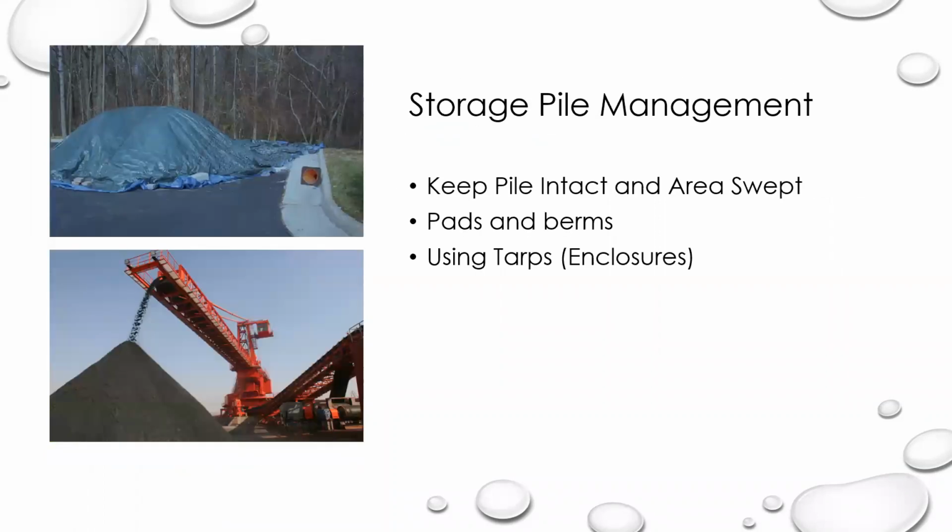You also want to manage your storage piles. Again, I've mentioned a few times, you want to keep it covered. But it's important to know if you're getting from it often, you want to make sure that you're sweeping the area around it and keeping that area nice and clean. You want to have pads and berms related to it and tarps and enclosures if possible. And of course, if you're constantly using a pile, this is not something that you can do like in the bottom left corner, but when you're done with it for the day, that would be a good time to tarp it over just to be sure, or to maybe even berm the area around where you're working so that it doesn't go off site.